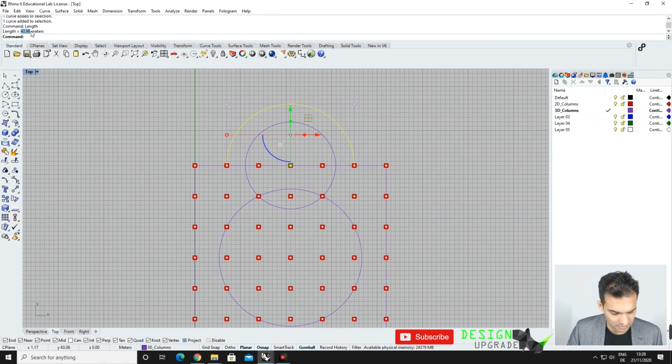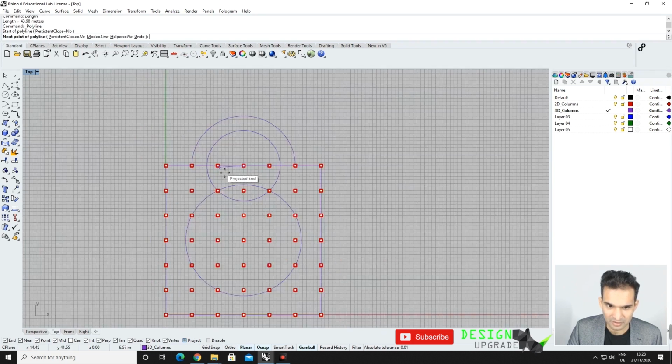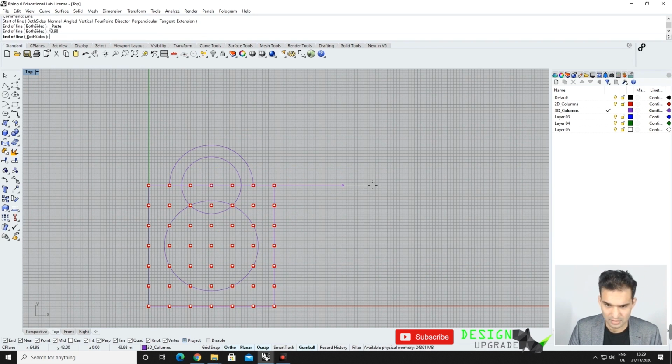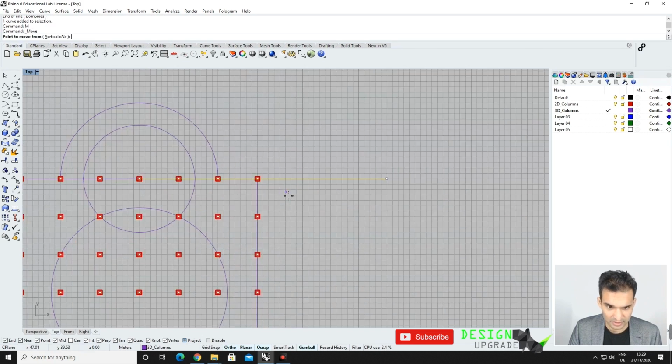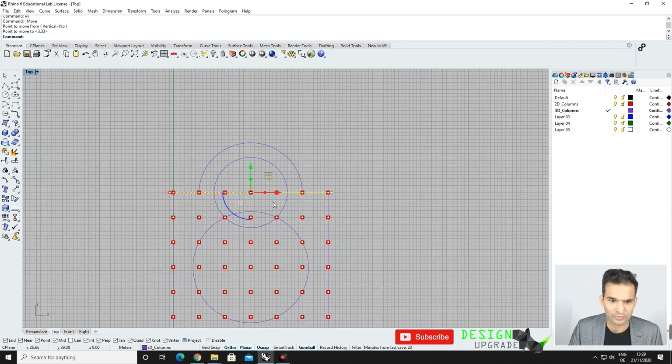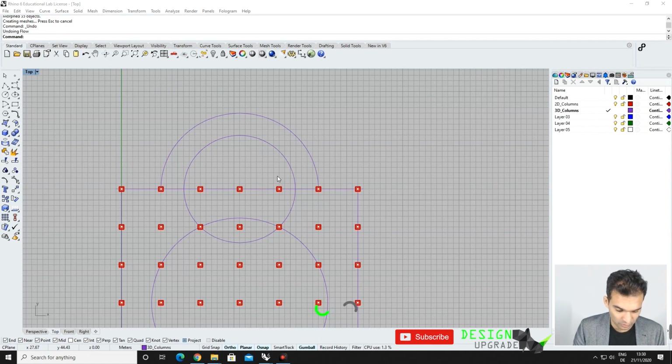Copy that. Now we are a bit more intelligent, so I know that I can just create a line starting from here, and lock maybe with auto this direction, and then just paste my length. I say here, and then I just take this center midpoint and just align it to my column, like so. So then we just hit flow again.